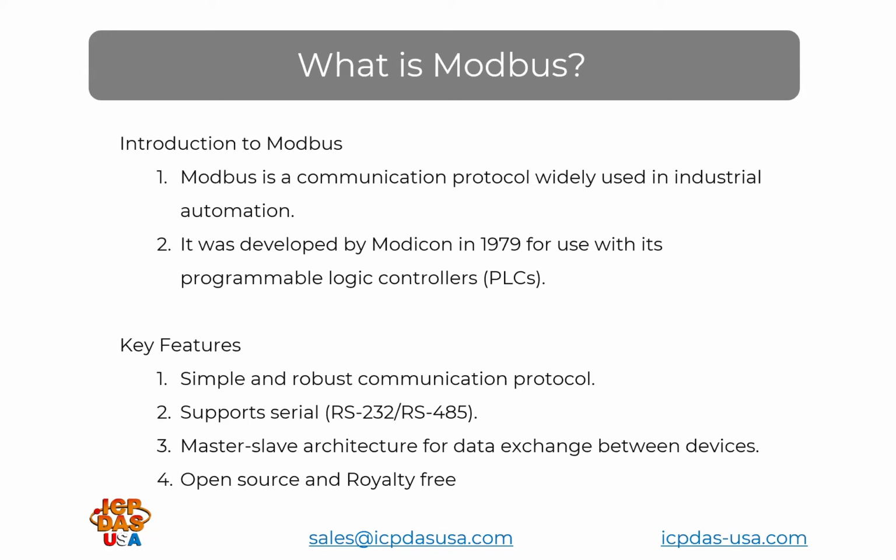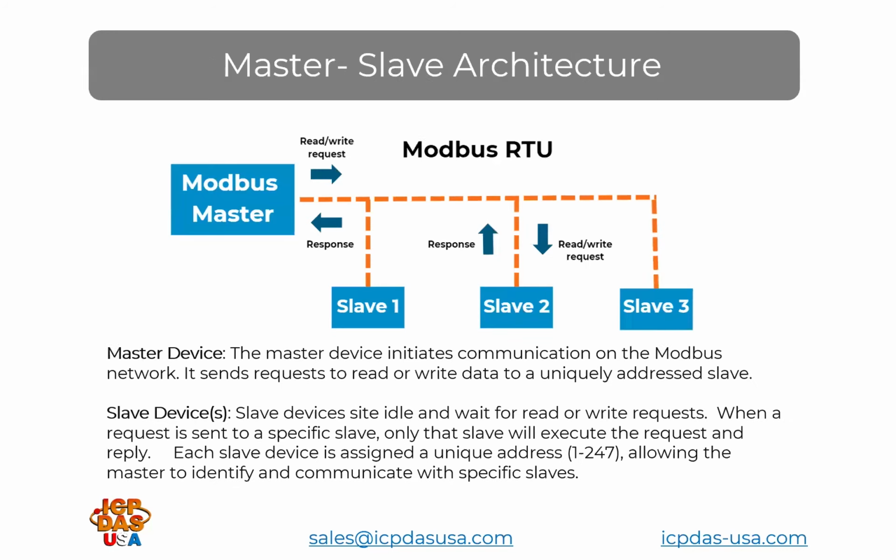Modbus RTU is most often used in RS-485 networks, but it's not fixed to RS-485. The main reason why Modbus became so popular and is still used today is that it's open source and royalty free. There are a plethora of free Modbus demo programs in various programming languages and automation software platforms.